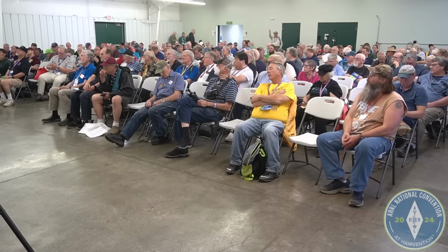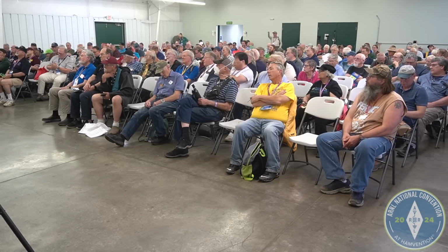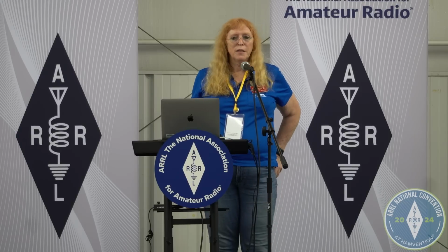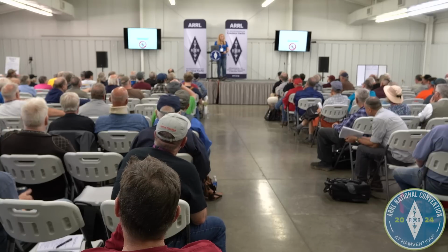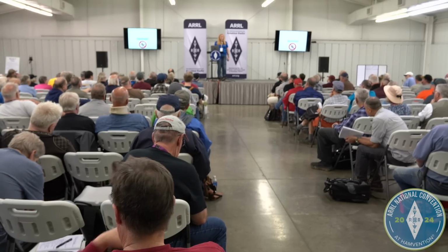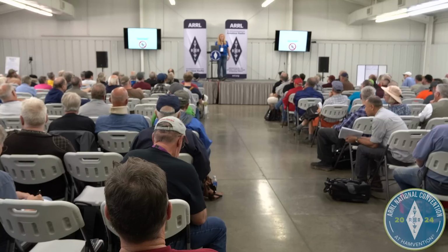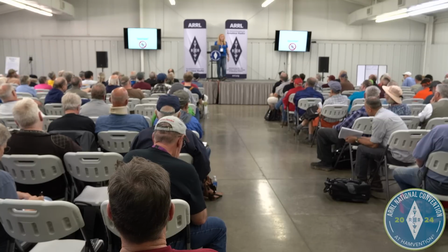Shielding I got, and ferrite was around power, where you lost me was with counterpoise. So generally, my way of knowing that I need one is I've got RF in the shack. I'm touching things and I'm feeling the burning sensation. That's a surefire reason to consider this. Other things, where the lights are lighting up and the alarm system's going off, generally that also indicates you have large field gradients nearby. In that case, you want those counterpoises outside the house if you can possibly do it.